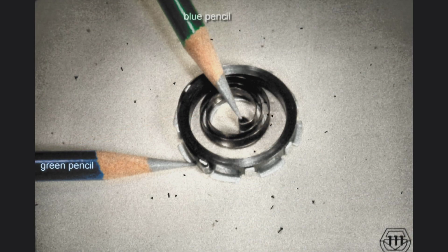Now let us turn to the reinstallation of the spring cage, with the spring inside it, underneath and around the rotate pulley. First, notice that the spring is held on one end at the point indicated by the green pencil, directly to the spring cage. The point indicated by the blue pencil engages with the hub of the rotate pulley. Notice also the wings, just like petals, which extend out at the outer rim of the cage. These wings provide ideal holding spots for the spring cage when it is installed at the bottom of the rocker.